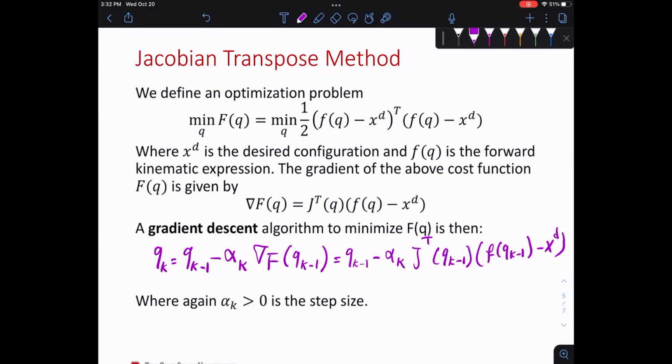Now, would we have any problem with the Jacobian here? No, you can just transpose it, right? It doesn't matter if it's square or not. So these are two distinct methods, yes. It's not the pseudo inverse Jacobian? No, this is transpose. So you don't have pseudo inverse, this is transpose. That's why we don't have that problem here anymore.